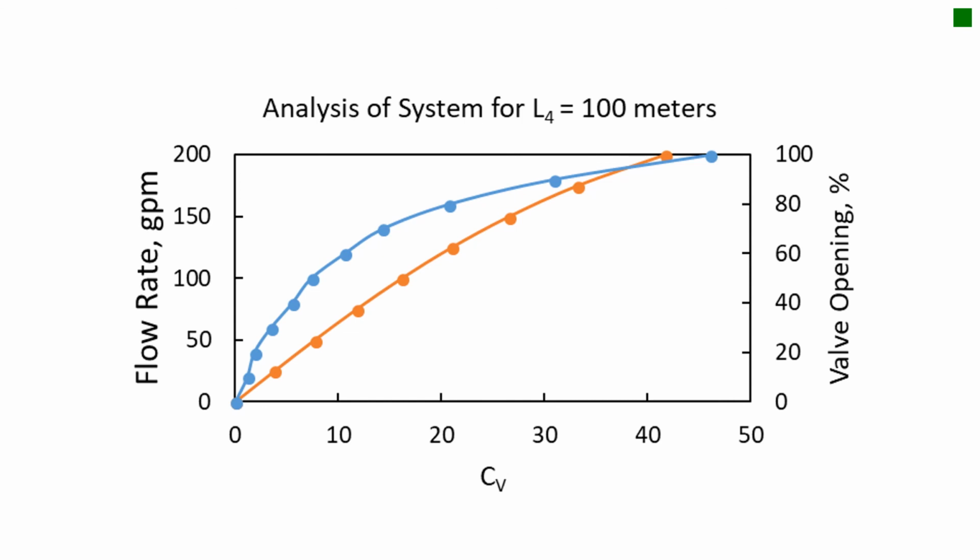My system curve remains the same. That's my calculated CV for different values of the flow rate. But look at the equal percentage curve, which is in blue. You can see that it has some curvature to it. Although my system curve shows some curvature, it doesn't show anything nearly as intense as an equal percentage valve does.